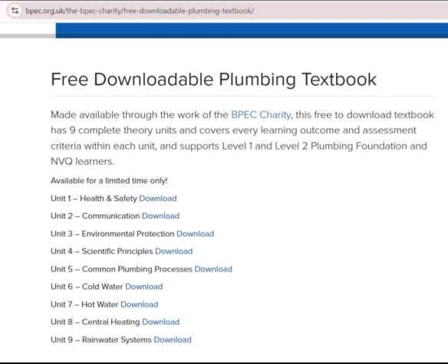A. Pumped heating with gravity hot water, semi-gravity. 2 pipe low pressure systems. A. Pumped heating with gravity hot water, semi-gravity. B. C-plan systems. 3 fully pumped low pressure systems. A. Fully pumped, 3-port valve, mid-position forward/diverting, Y/W plans. B. Fully pumped, 2x2-port valves, S-plan.